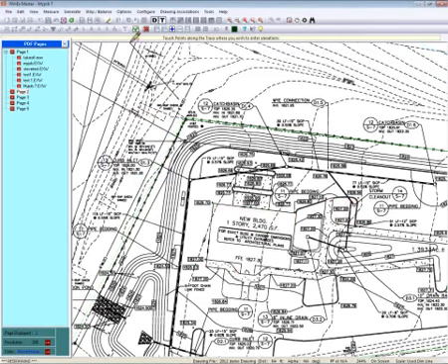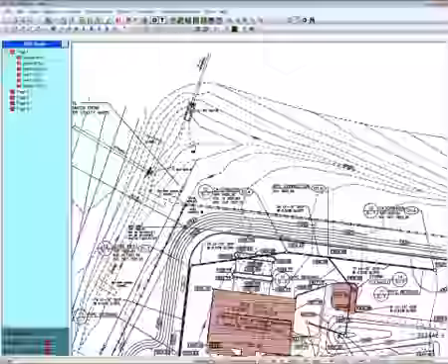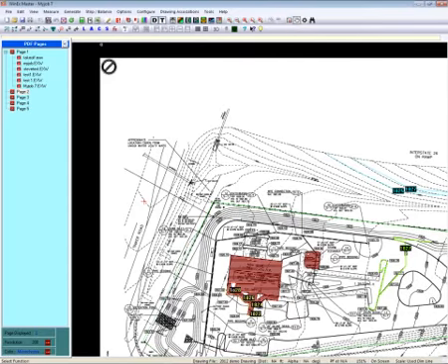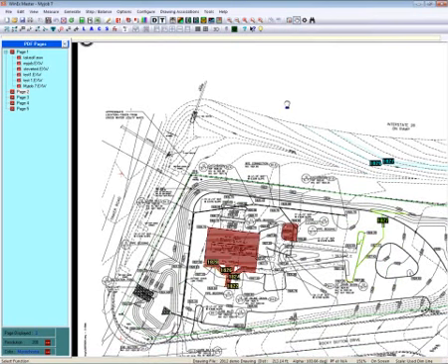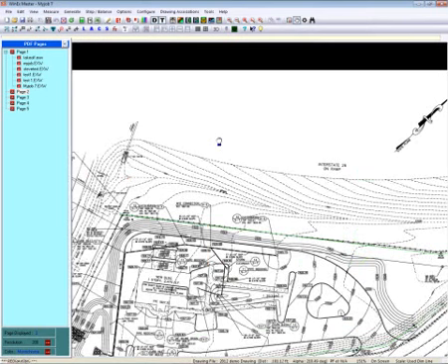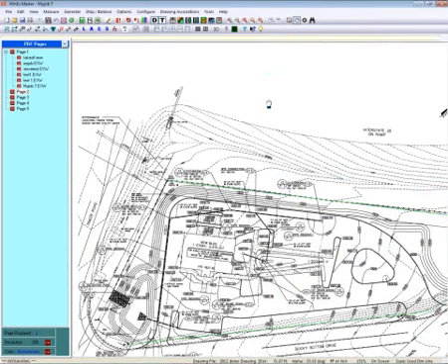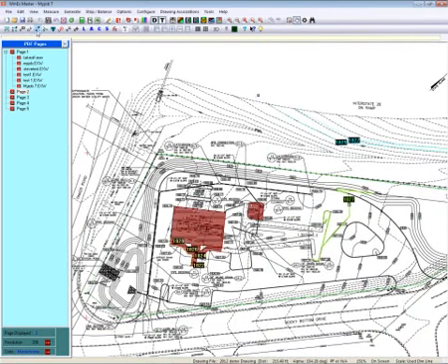So now, when we give you the cut and fill quantities for this site and the maps, we'll give you along that gradient those elevation changes and what that does to your cut and fill quantity. So very, very easy to do. And again, you can put connected spots all over this. By the way, when you're in the hand mode, you're in the grab mode. So if you hold your left mouse button down and drag it, you can move the drawing anywhere that you want to. Now, one final thing I just want to bring to your attention.